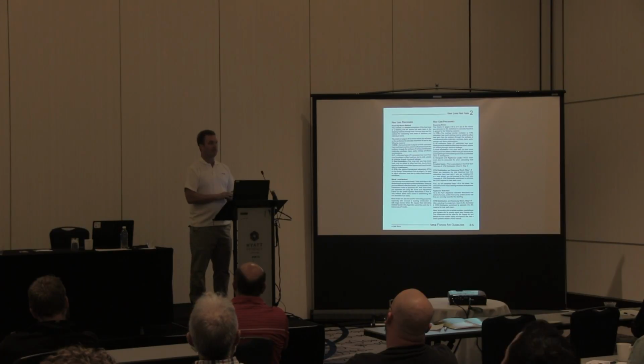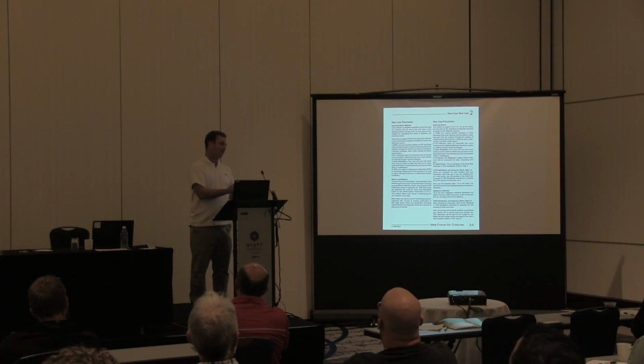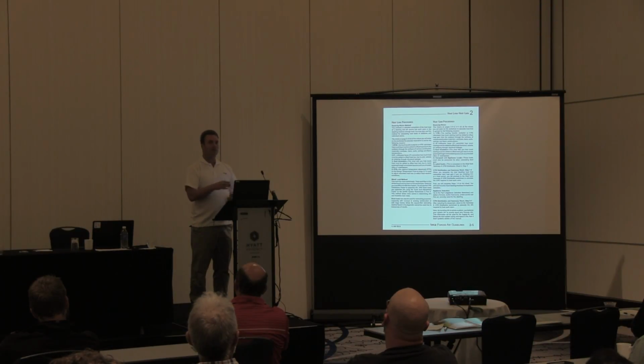when the guy comes in and says he's going to put a 50,000 BTU furnace in, and you did the quick one and it showed 55. Well, whatever, it's probably close enough because the quick one isn't as accurate. But if you come in at 100, then there might be a problem, right? Or maybe there's time for a discussion to say, are you sure? Or even the other way, where he said 100 and you do it at 50.